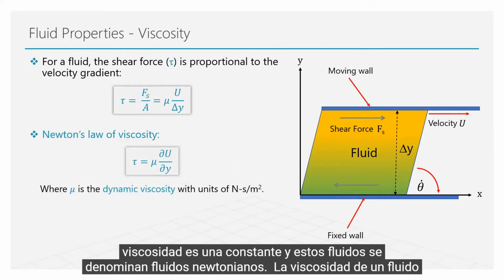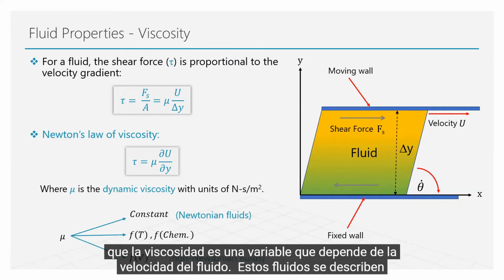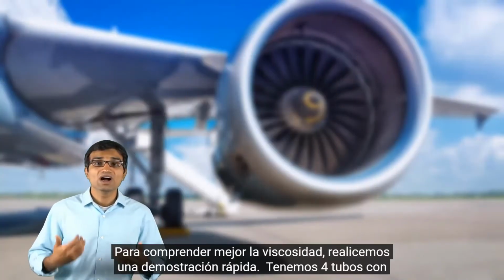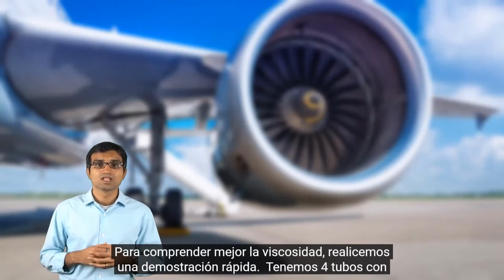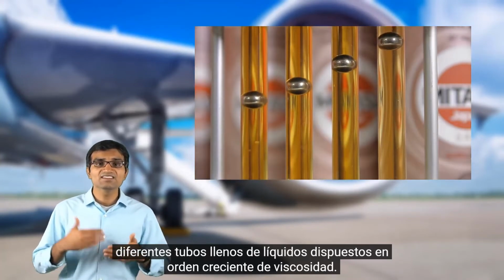For most fluids, viscosity is a constant, and such fluids are called Newtonian fluids. Viscosity of a fluid can also be a function of temperature and chemical composition. There are, however, other fluids for which viscosity is a variable and is dependent on the velocity of the fluid. These fluids are described as non-Newtonian fluids. To understand viscosity better, let us perform a quick demonstration. We have 4 tubes with 4 different liquids arranged in the increasing order of their viscosity.